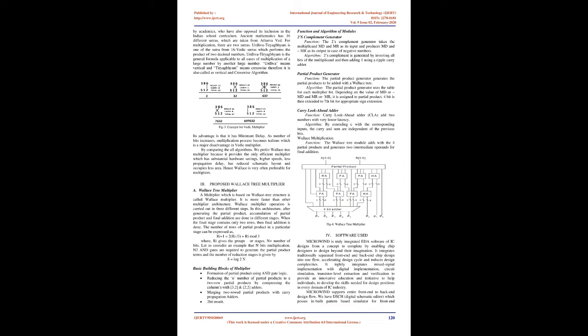It initiates with the ability to both add and subtract. There are multiple ways to calculate a product. This multiplier can scan 3 bits at a time, hence the delay decreases. But the power consumption of this multiplier is more, hence the efficiency of the system reduces. Example, 3 x minus 4. M equals 3 equals 0011, R equals minus 4 equals 1100. Multiplication can be implemented by repeatedly adding one of 2 predetermined values A and S to a product P, then performing a rightward arithmetic shift on P.